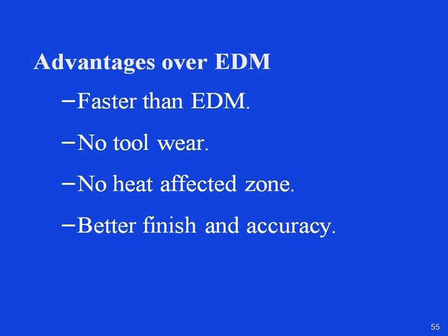Large cavities are more economical on ECM and can be processed in 1/10 of the time that is required in EDM. That means it is considered to be highly economical with respect to the EDM process. And the other advantages over the EDM of this ECM process are, it is faster than the EDM process, as we have seen just now. It could be as high as 10 times.